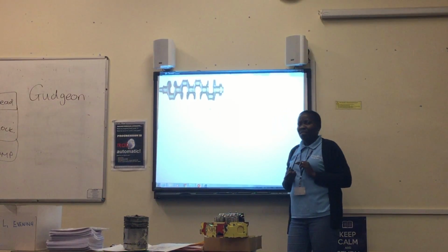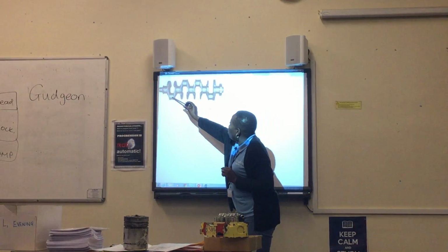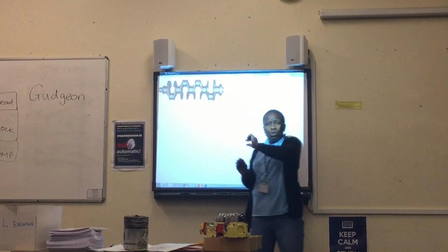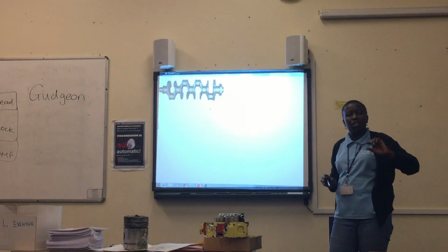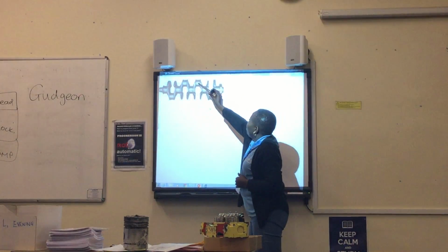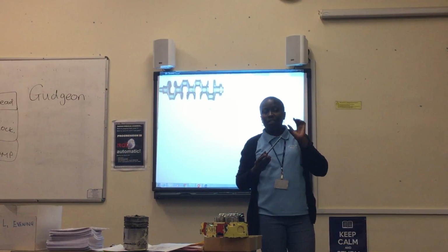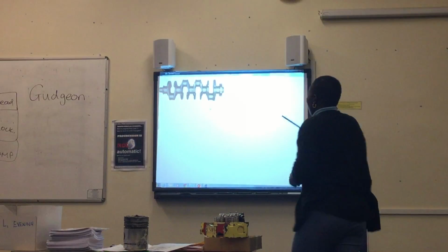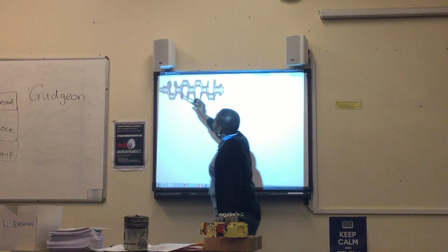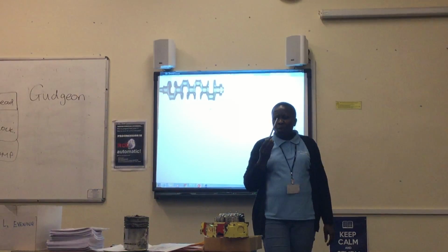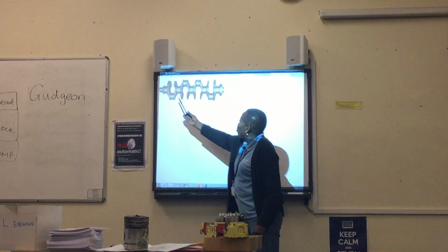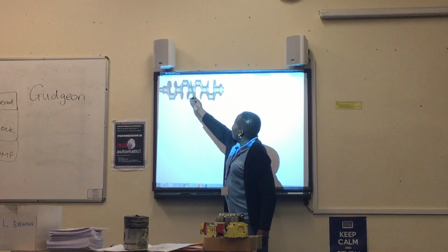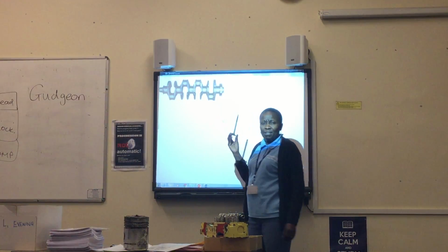Then, can you see that we have that one, piston one, which is offset, this one, piston two? They are not along the center line of the crankshaft. We call these offset ones the big end bearings, or big end journals, or crank pins. So we have big ends, then we have the mains. The connecting rod is connected to the offset ones. Connecting rod there, connecting rod there, connecting rod there, connecting rod there.